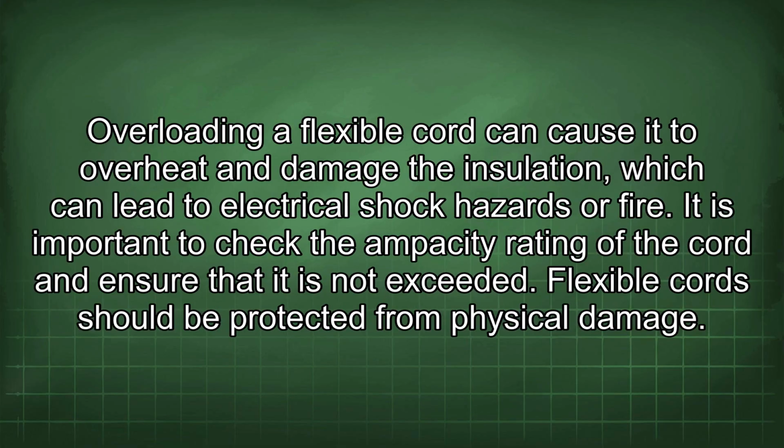Flexible cords should not be overloaded. Overloading a flexible cord can cause it to overheat and damage the insulation, which can lead to electrical shock hazards or fire. It is important to check the ampacity rating of the cord and ensure that it is not exceeded.